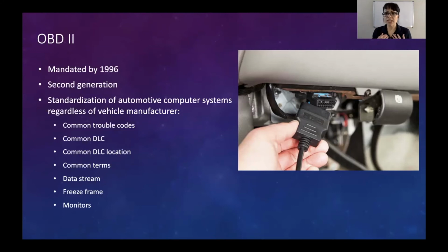So when I'm diagnosing sensors, this is usually the first place I go because it's really easy. You plug in the scan tool. If the code is for a MAF sensor, I'm going to take a look at what the MAF sensor signal is reading from the PCM, and then I'm going to go test the sensor to see if it's the same signal and if it correlates, right? Is there something wrong with the wiring? Is there something wrong with the sensor itself? The PCM can only make decisions based off of what it's told. So rarely you'll run into issues where it's the PCM. It happens, but it's generally not the most common thing that happens.